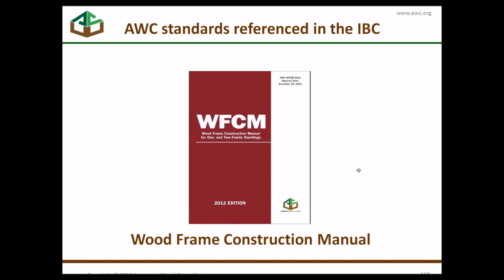The loads are calculated for all geographic locations now across the country, and it contains the tables and so forth necessary in a prescriptive way, similar to what we're used to for residential construction. It has the span tables and so forth, the connections. It has the appropriate tables to put together a building using the engineering, the loads and the engineering criteria of the model codes and ASCE 7. Being prescriptive, it's a little more accessible, perhaps.